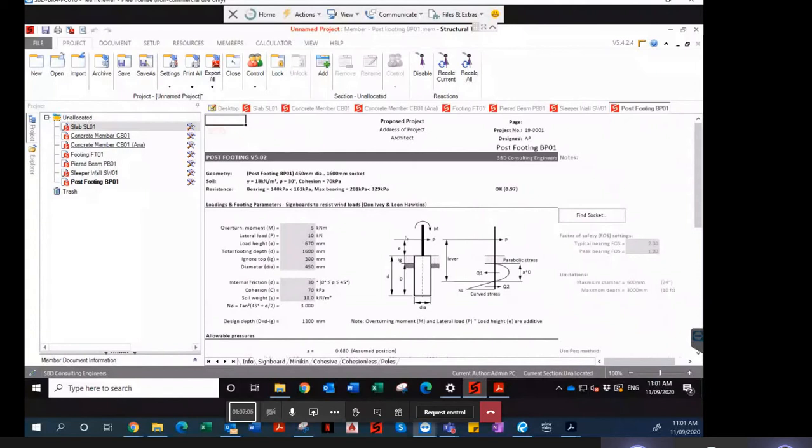Does it make sense? So this particular shape works well when the footing is deep. But when the footing is not deep, then you've only got the triangular passive force acting on one side, and then your force is sitting at 1/3 the height. So it's similar to what Paul has done.